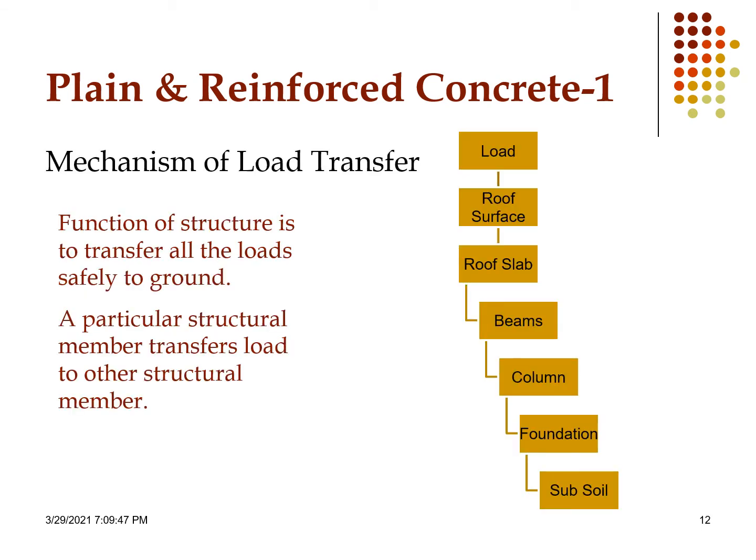Now, load transfer mechanism. Load is actually transferred from top to bottom. So first of all, from roof surface to roof slab, then on beams, then on columns, then on foundation, and then it is basically transferred to the subsoil underneath the foundation.